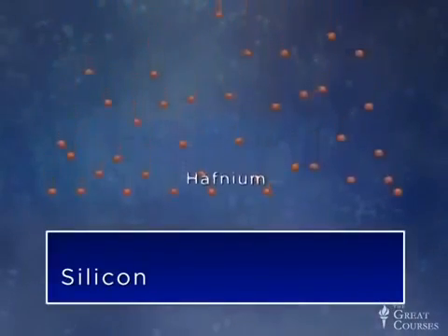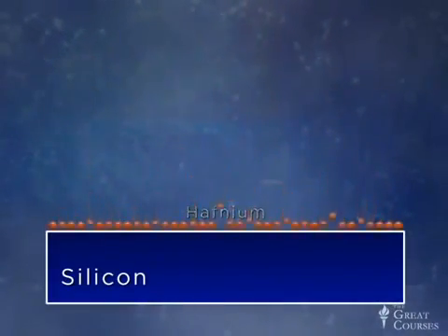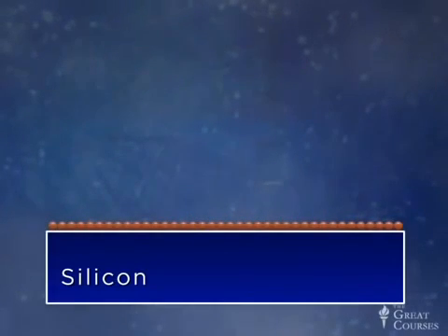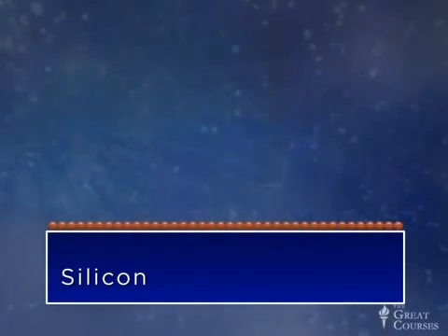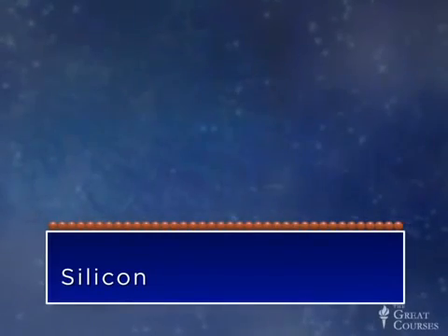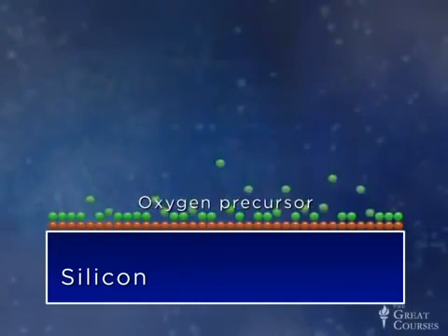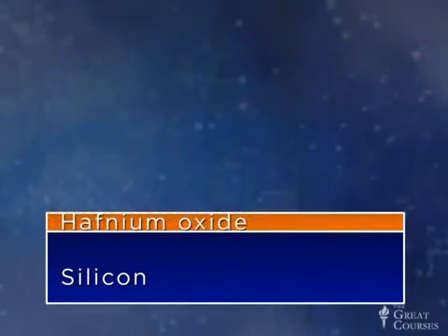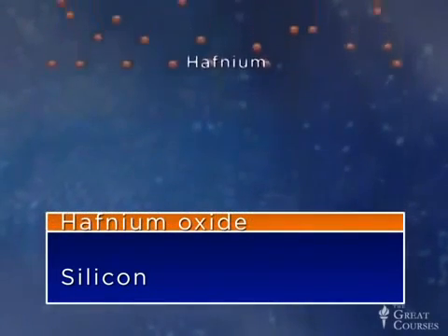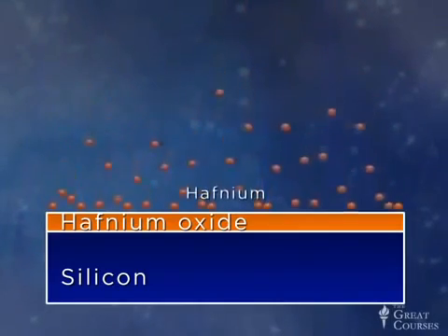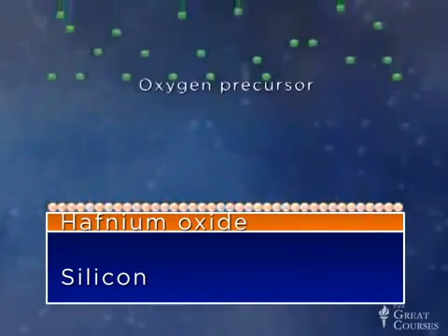And so it's a two-component material. Hafnium is one of the elements in it, and oxide is the other. And folks have figured out through this atomic layer deposition process how to put down exactly one first layer of the hafnium, which then is very prone to react with oxygen, and then to waft over it a little bit of water or another oxygen precursor and react that first half layer to form a full layer of hafnium oxide, and then to start again.